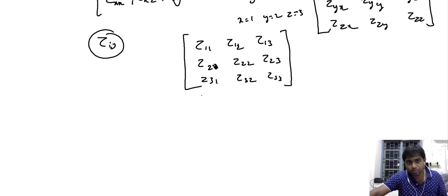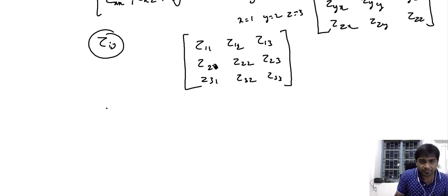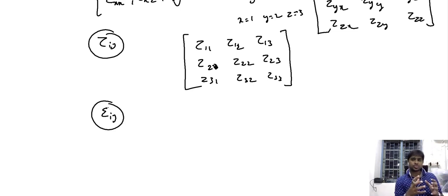Now, similar to the stress, it is also possible for us to show that the strain is also a tensor. The tensor nature of the stress comes from our focus, again, because we want to have a generalized understanding, a generalized description of the stress. We consider a generalized loading condition. The generalized loading condition is a triaxial loading condition, and we have considered a plane that is inclined.